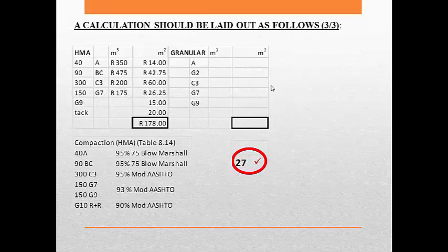the subgrade pricing and the compaction, and also it would be nice to then calculate the final quantities of the pavement. And the final quantities of the pavement is typically in meters cubed. We're given the area of the pavement, length by breadth, and here we have the depth, so it's a simple length by breadth by depth to get final meter cube quantities of the pavement layers.